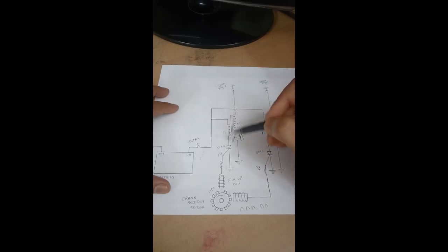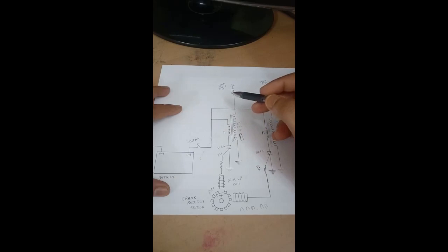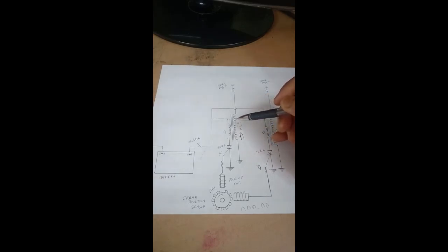Now in this case, for each cylinder there is an individual high tension coil. So there is a very high intensity, healthy current at the output of the secondary coil of the high tension coil. So this ignition system performs very well at low RPM as well as at very high RPM, because there is no distribution of the secondary voltage to the various cylinders. Each cylinder gets its own high tension coil. So this is all about the distributorless ignition system. Thank you.